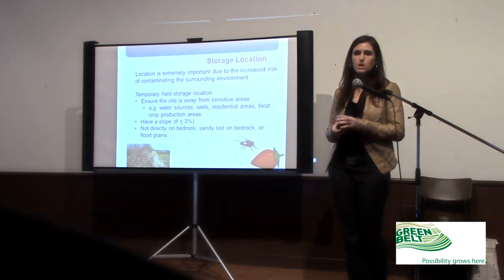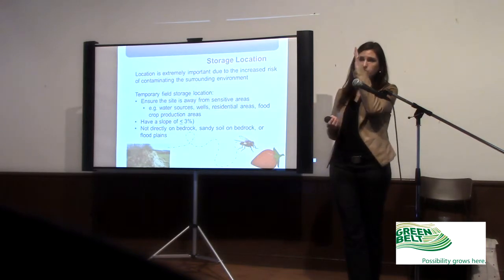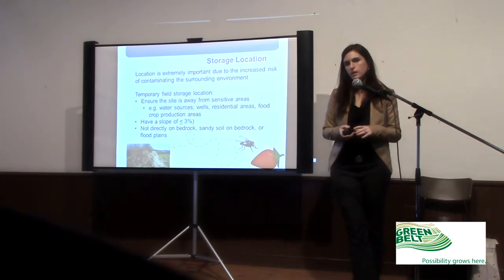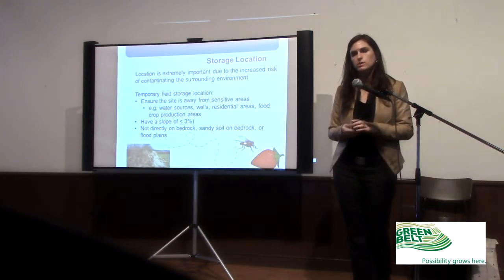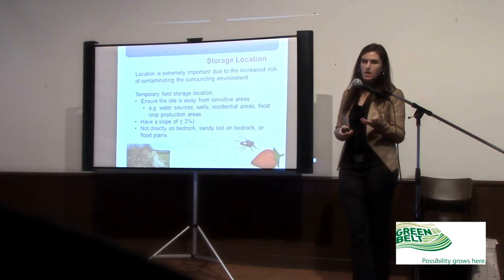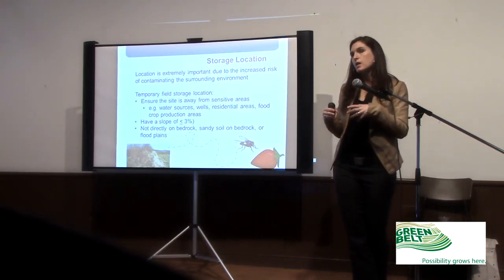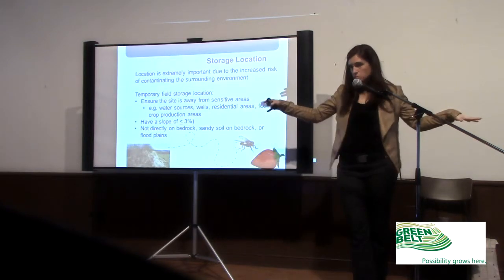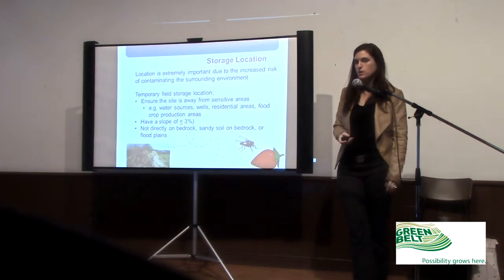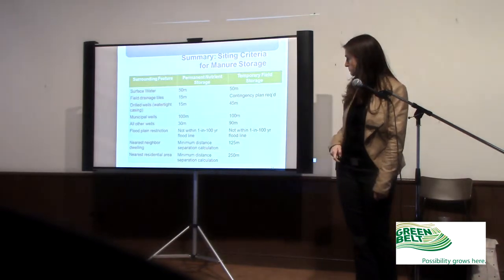They do talk about having a slope of less than 3%, because if you have a huge slope, it's just going to run off and be gone, and that really increases the chance of contaminating the environment. And then the other requirements, like avoiding placing it directly on sandy soils or bedrock, because it's really not going to go anywhere, and it's just going to push it outwards and cause more leachate and runoff than if it could actually be incorporated.